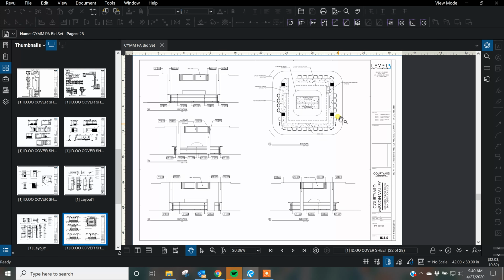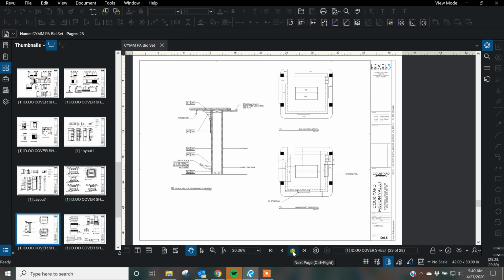So here's the new bar. This new bar that we were talking about. We've got elevations on all 4 sides of this bar, including this really cool TV ceiling element. And then you get a little further into detail. This is a section. So if you cut through a section of the bar and look at it from the side, this is what that would look like. Again, everything is called out. This is the laminate. This is a metal reveal, wood finish, stone top, drink rail, FRP panel on the backside, quarry tile base on the backside.